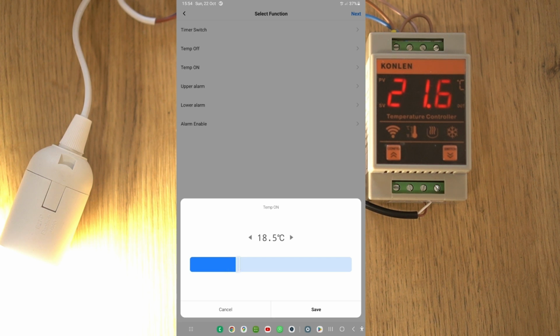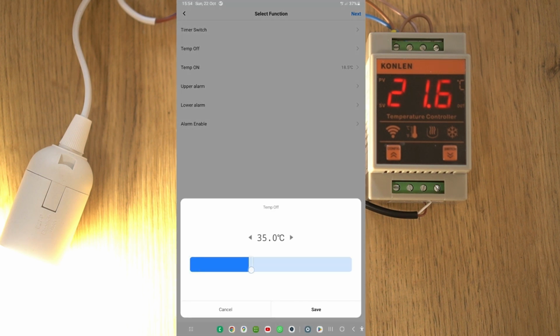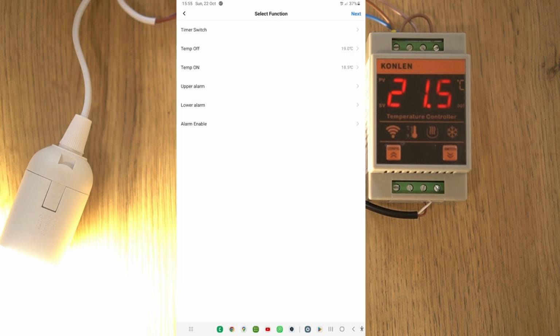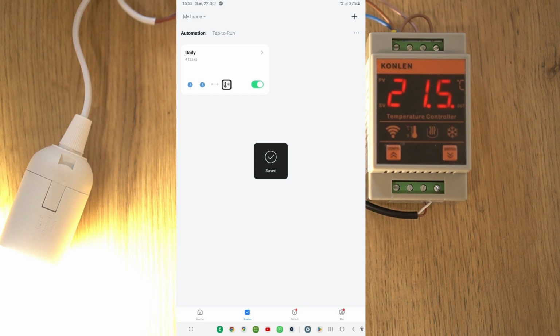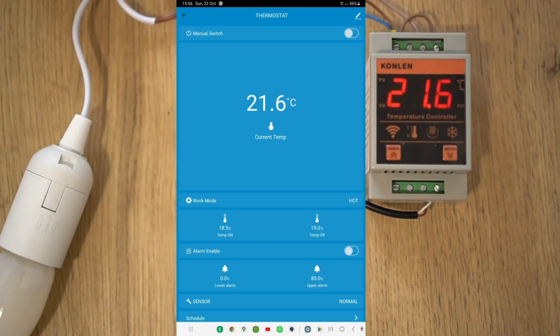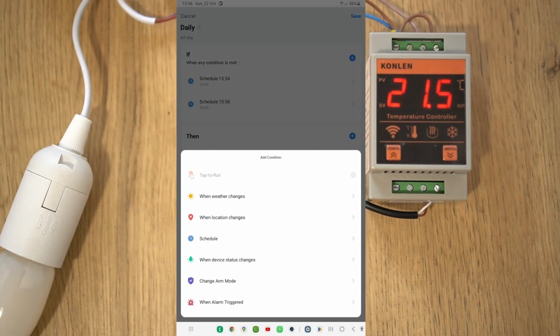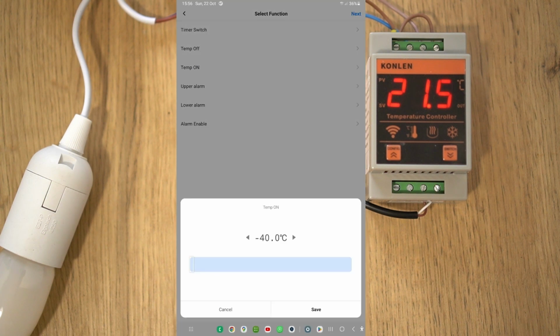So, as you can see, the boiler has switched off. Now, let me show you how to turn the boiler on. I'll show you that it will operate within the temperature range that you've set. Suppose it will switch on at 59 degrees and switch off at 61 degrees. Save it. Wait until it's 15:58. Here's how you see the boiler has switched on, and I'm heating the temperature sensor to simulate the boiler heating process. The boiler switches off as the temperature reaches the set point.